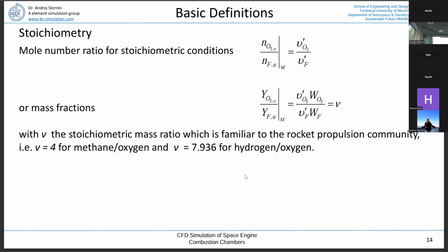And as I already made the argument with the small molecular weight of the exhaust gases, if we add more fuel, we are basically decomposing the carbon dioxide, and as a product, we get more carbon monoxide than carbon dioxide. That's a significant reduction of the molecular weight of the exhaust gases, and that raises the performance. So in a rocket engine, we are doing better if we throw in more fuel. This gives us a higher efficiency.